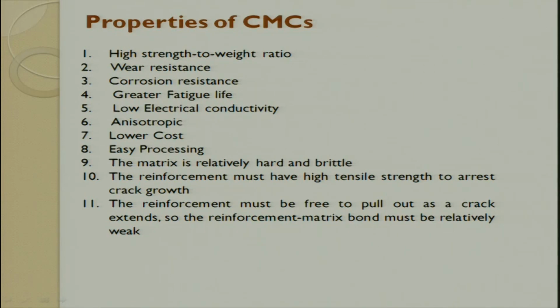So, what are the properties of a ceramic matrix composite? Generally, when you make a product, the first thing you have to do is write down the objectives, or the specification. What is the specification this product has to execute when put in service condition? So, we will always list down all the properties you want from this material, plus put a quantifying value for each specification. With this you get the properties. Once you have these properties, you start working on which matrix to choose, which interface to choose, what is the processing route, and how to meet the requirements.